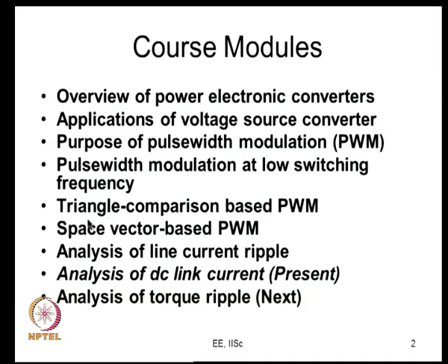So, today we may have to have a quick look at some triangle comparison methods also, and also maybe space vector based PWM for the purpose of our talk here. Space vector based PWM is another way of generating PWM signals. These two are the widely used approaches for generating them, and as we have discussed, most methods can be done in both ways, like sine triangle or third harmonic injection, etc.